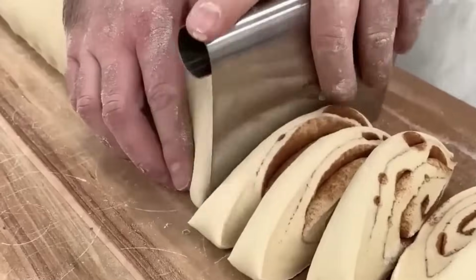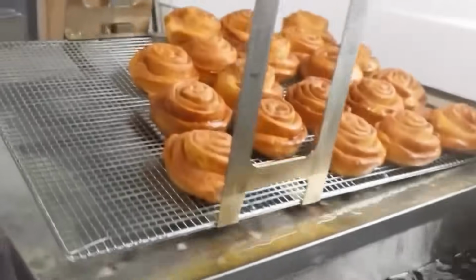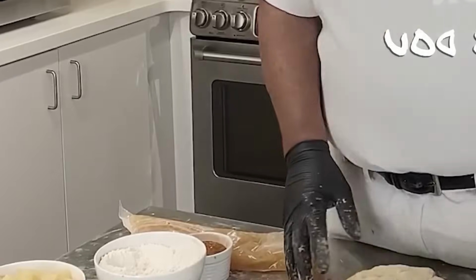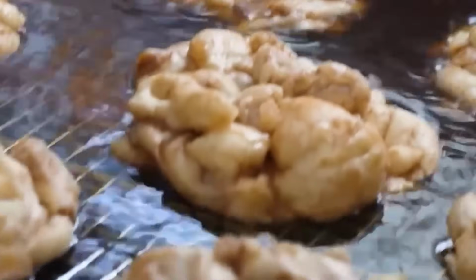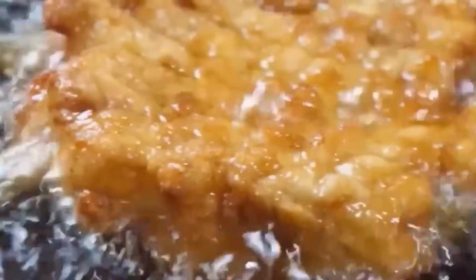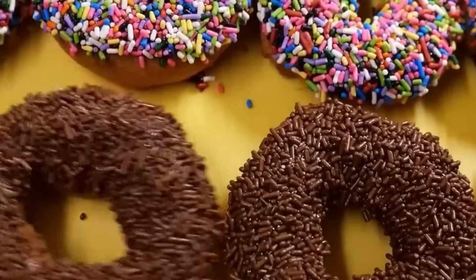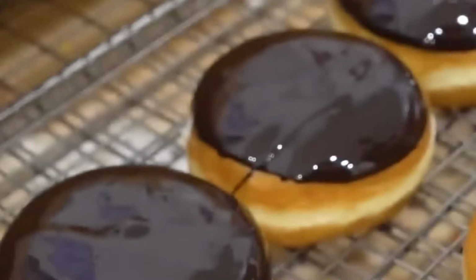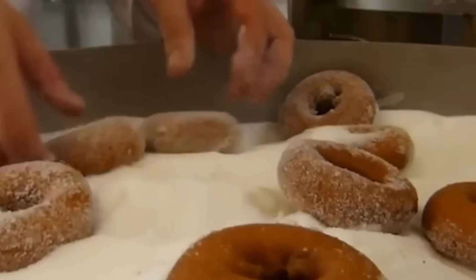For varieties requiring toppings, donuts travel under a vibratory topping applicator. Toppings such as chopped peanuts, sprinkles, or coconut shavings are dispensed via a rotating auger or oscillating tray, which evenly distributes material across the icing surface. Adhesion is achieved by timing the topping deposit immediately after icing application.